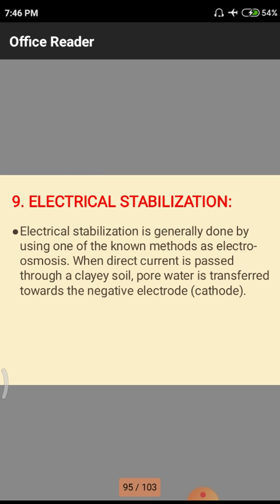But in the opposite case, where a huge amount of water is there, we are not removing that water, we are simply freezing it by using freezing techniques with the help of some chemicals, inserted into holes at huge pressures. Automatically those chemicals freeze and the total water will be in solid state, so there will be no movement of water, no erosion process, no segregation. Automatically the total soil will be strengthened.